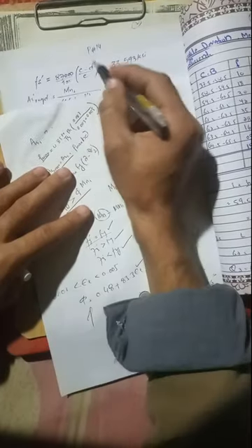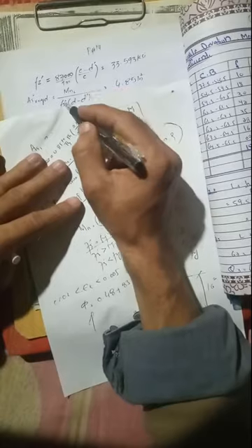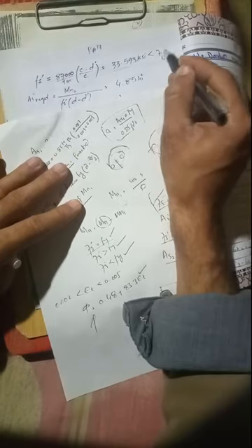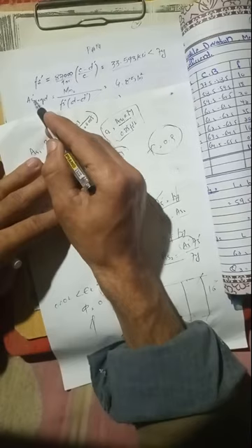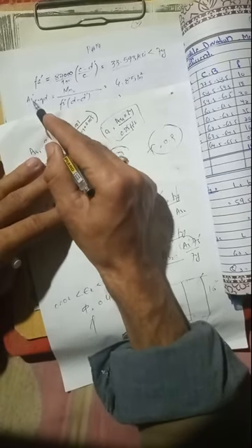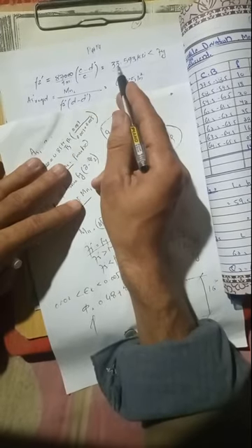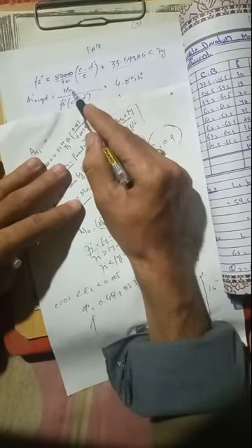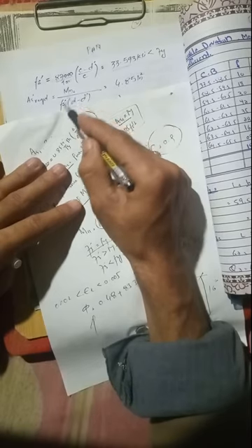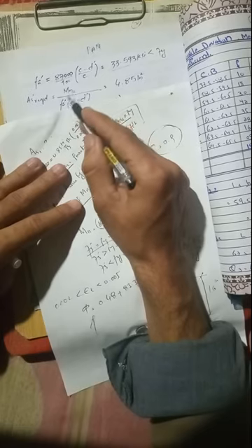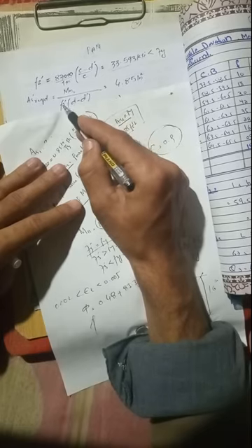So we already know the values of c and d prime, and Fs prime is required, as we did in the previous example. Remember, this is less than Fy. This is interesting, right? So that's why we have to calculate Fs prime, and when you calculate Mn2, we have to use the actual value of Fs prime, not 60. Remember, Mn2 and Fs prime, these two are very important because most of the students make this mistake. They use Fy value.